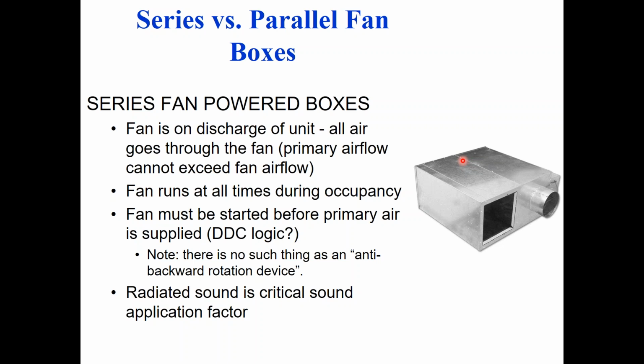Now, sound on these guys. There's a school of logic that is, well, if I have a series fan power box, the fan's on all the time, so my occupants will hear it, versus parallel, where it'll only be on sometimes and they won't hear it very much. It's actually the opposite logic that holds true.